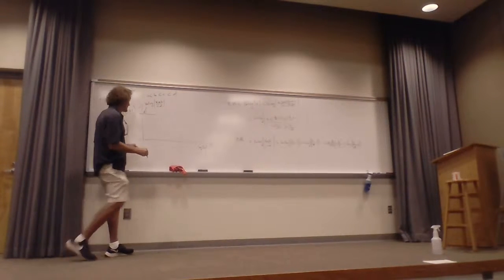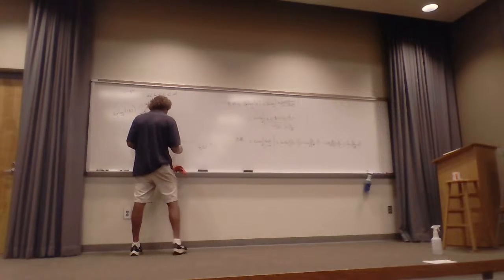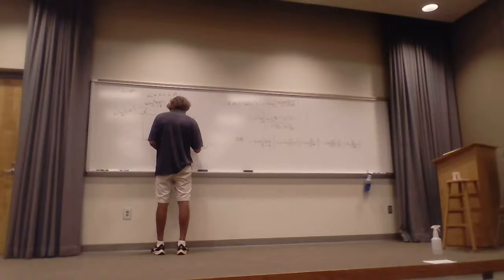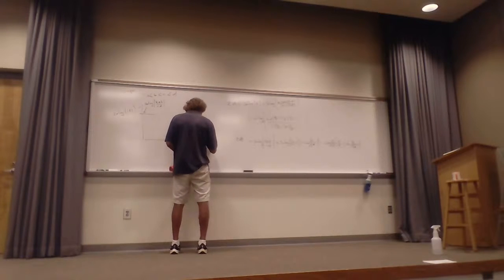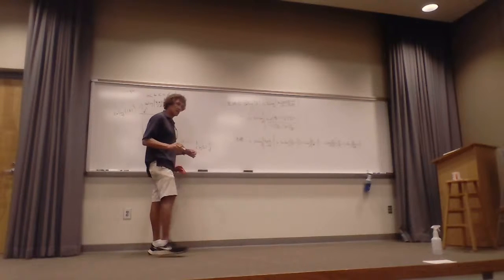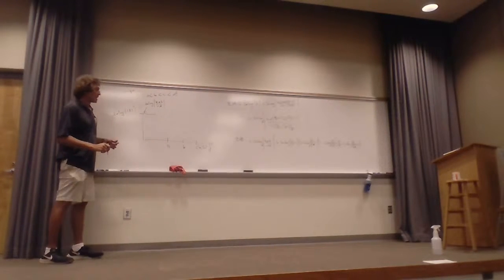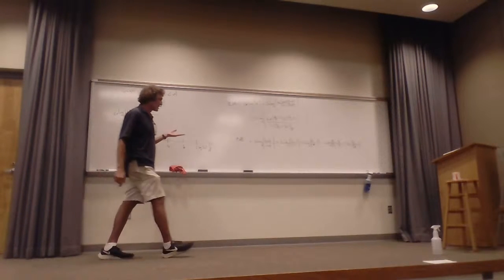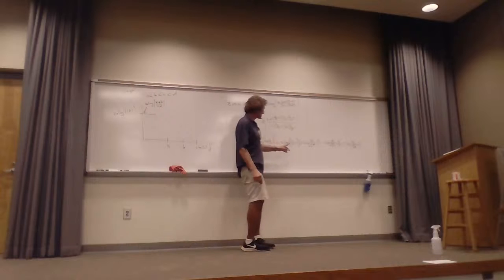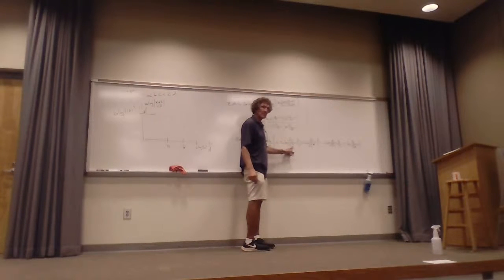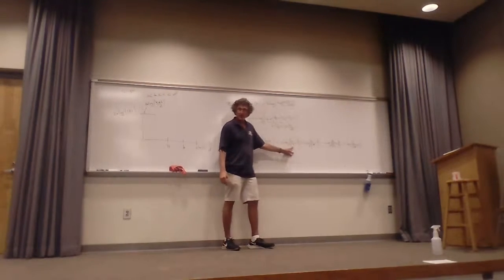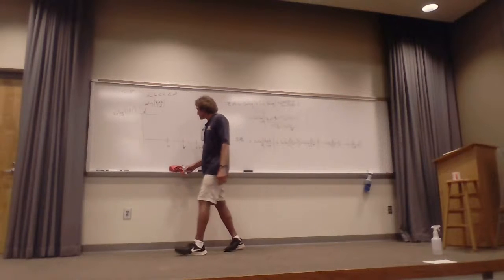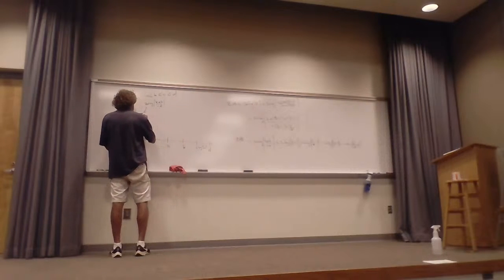Now A is first, so here's A, here's B, here's C, and here's D. I come in flat, and the first thing I hit is a zero, so it starts increasing at 20 dB per decade right here. Do y'all see that? So actually, let me do it down here. I'm going to say this is my point of entry.